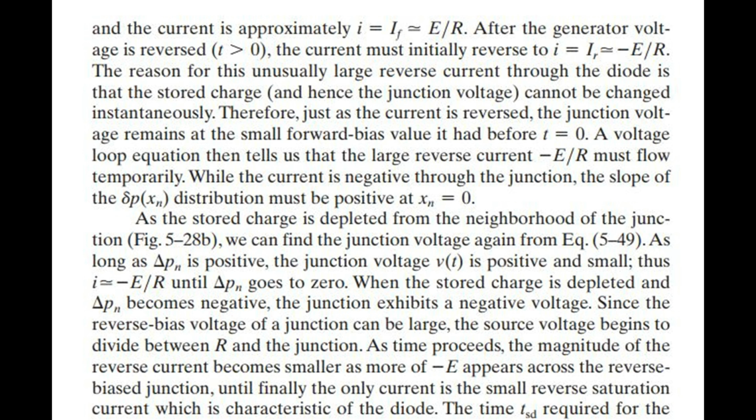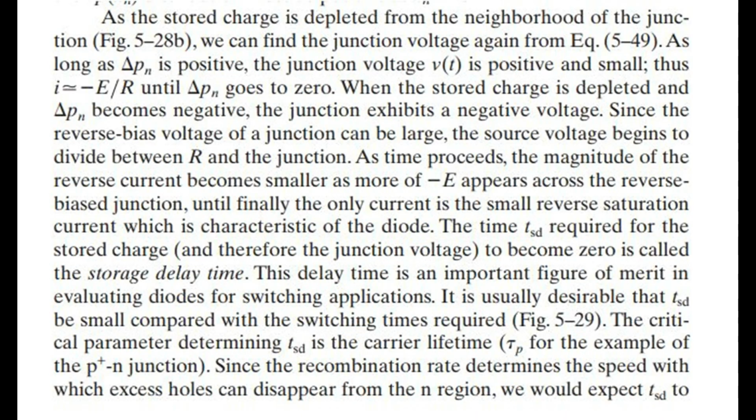The time t_SD required for the stored charge, and therefore the junction voltage, to become 0 is called the storage delay time. This delay time is an important figure of merit in evaluating diodes for switching applications. It is usually desirable that t_SD be small compared with the switching times required, Fig. 5.29.